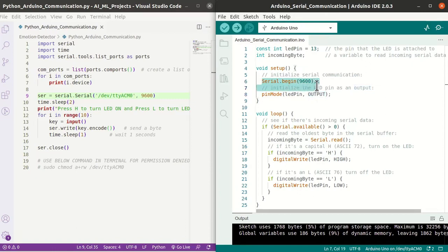And we have declared that the serial communication begins with a baud rate of 9600. So that is our baud rate. Baud rate is bits per second. You can consider it the speed of communication between two devices while they are doing serial communication. So it is mandatory to define it here, and ideally we use 9600. There are multiple options for baud rate that you can Google or search, or I'll explain it later. The default is 9600, which we use for serial communication.